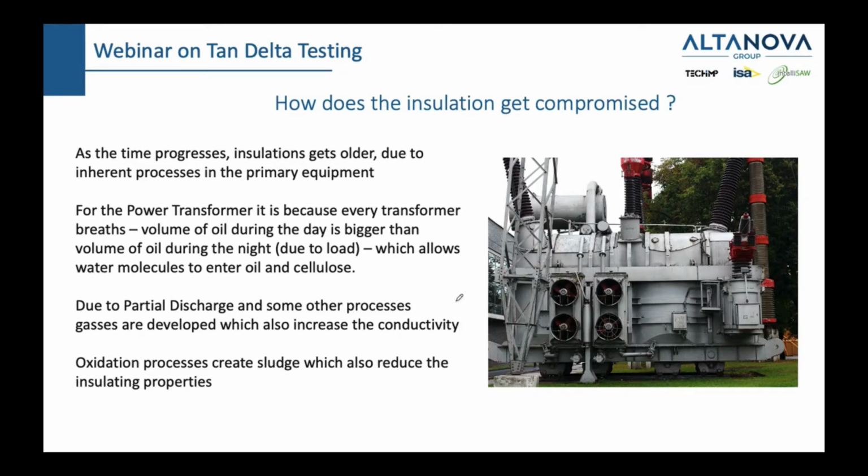But then the night comes, the temperature drops, people go to sleep, and the transformer is not used at 80% anymore, but maybe 20 or 30% of its nominal power. And since the temperature reduces, the oil reduces its volume. Then again, the morning comes, the oil increases the volume, the night comes, it decreases the volume. So I hope you follow me and understand that this is a definition of breathing.